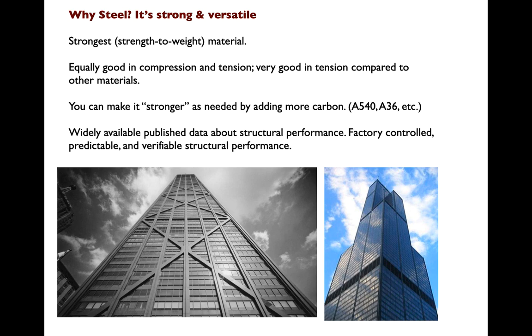If you think about reinforced concrete, for instance, we have to be very conscious of where we're putting the reinforcing steel in it. We have to think about the loading conditions and tune a beam based on that, where we put the steel, where we anticipate tension to be. If we're designing that same beam or girder out of steel, it doesn't really matter. It's going to be equally strong no matter which way the element is in bending.